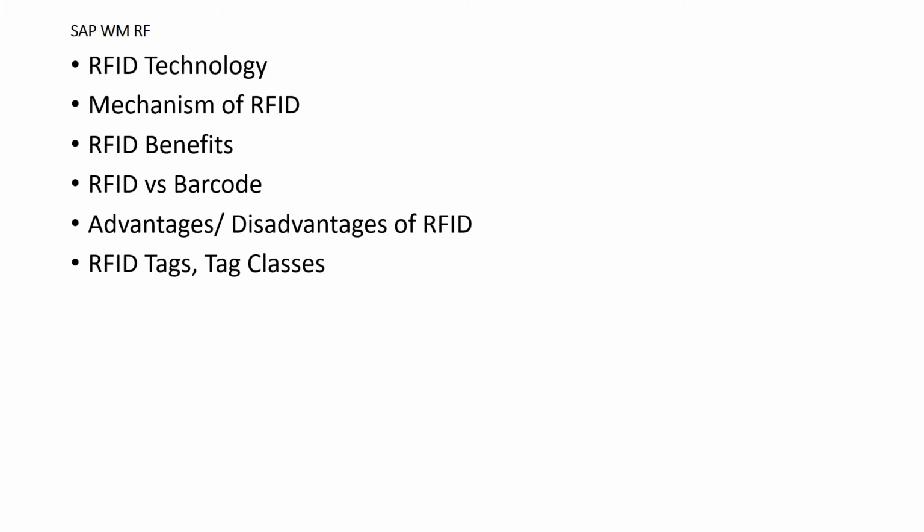The ability of RFID not to require a line of sight is also a disadvantage. An RFID reader will read all tags within its range, and this may be problematic if the wrong tag is selected. Therefore, line-of-sight reading is preferred for some RFID applications. If an RFID tag fails, it is not as obvious as the failure of a barcode. If the RFID tag is not seen, then there is no check to know that the tag has failed.